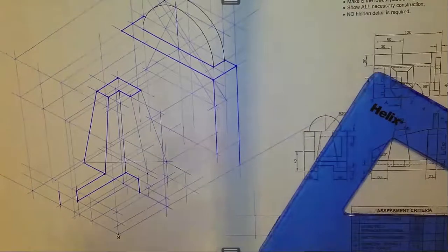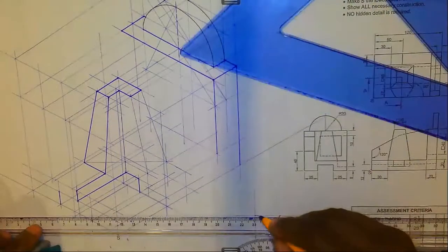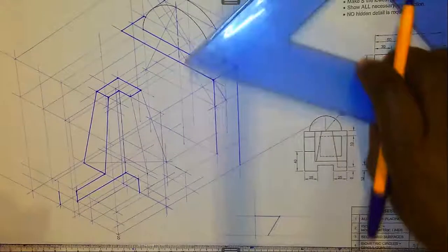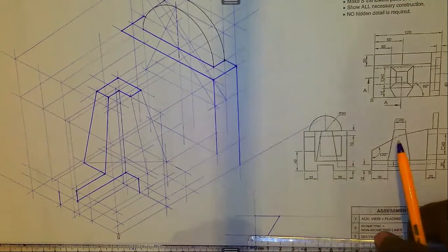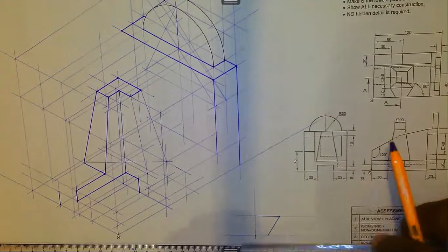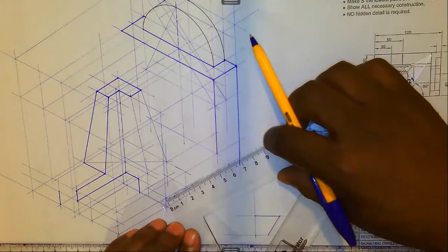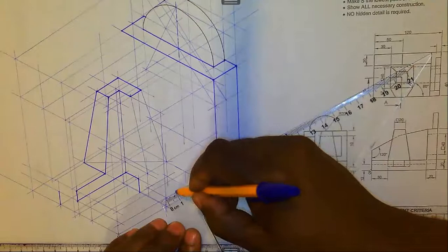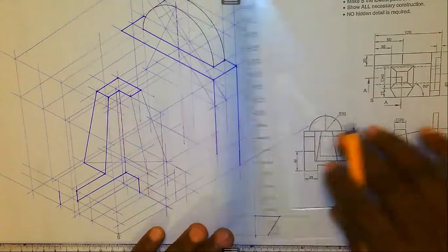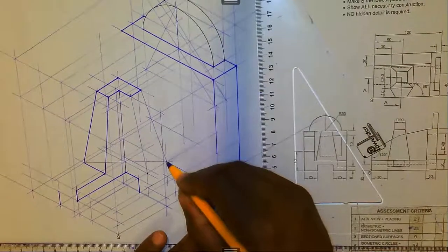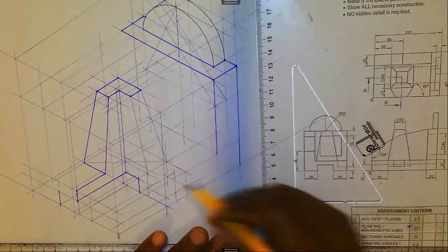That is our auxiliary view, which means from the point of cutting, from the center line, we need to measure from here to there, that distance. We can measure using our measuring instrument, but it's roughly 10 millimeters. We come here, measure also 10, then we project up like that. Now, this point is connected to there, and this one is connected to this one.